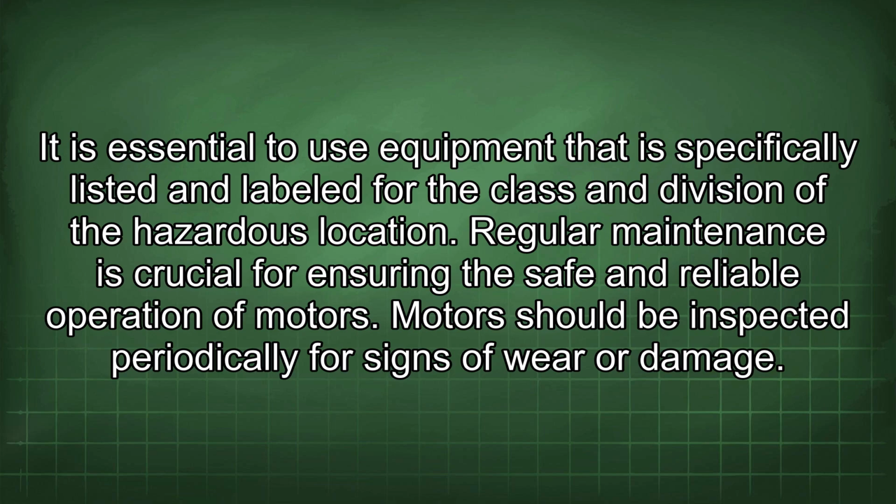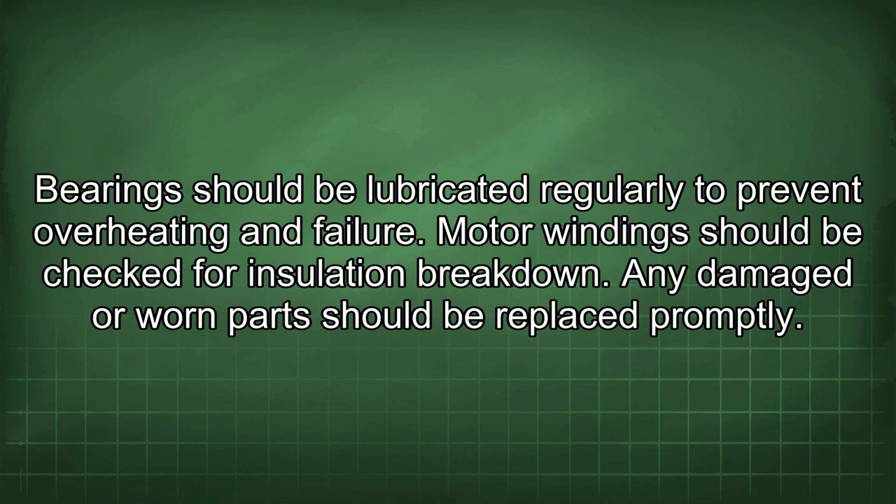Regular maintenance is crucial for ensuring the safe and reliable operation of motors. Motors should be inspected periodically for signs of wear or damage. Bearings should be lubricated regularly to prevent overheating and failure. Motor windings should be checked for insulation breakdown. Any damaged or worn parts should be replaced promptly.